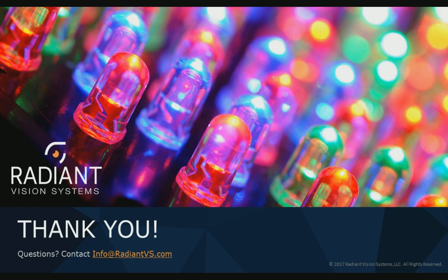Right. If you build a ray set, you're actually getting spatial information. A ray set is going to have the rays listed in terms of their origin, their direction, and their intensity, while an IES file is basically, again, that point source approximation. There is just an intensity value at a specific angle. So yes, you are getting more spatial information with one of those exported ray sets, and we are always accepting suggestions as far as additional file formats to export to, and we do take that into consideration.